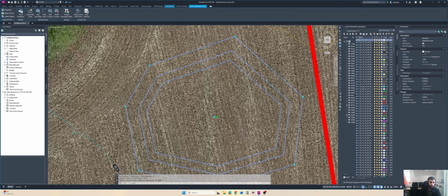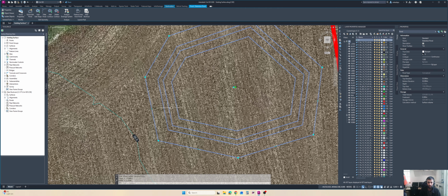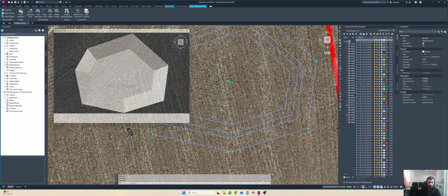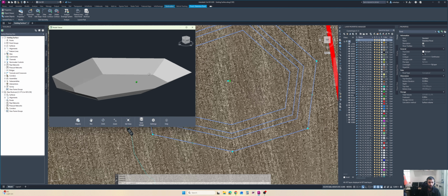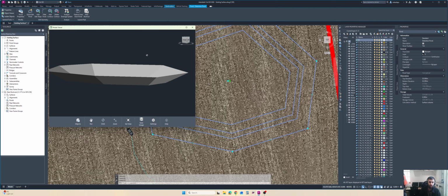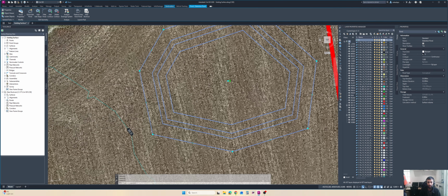So now if I quickly add the side slope, it says select the contour. I have selected my contour. Now the slope is like this. If you want to expand it or close it, just click here. So now we have added the contours as well. Now if I look into the 3D, you can see it comes up very neatly, very nicely. So it all depends. We don't have to work with the feature lines. We just have to work with our pond settings.